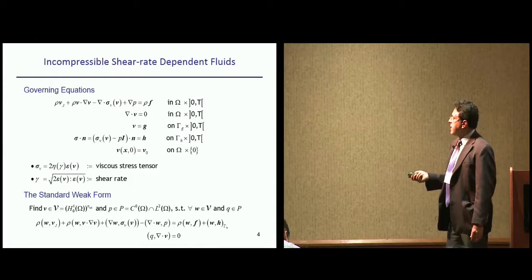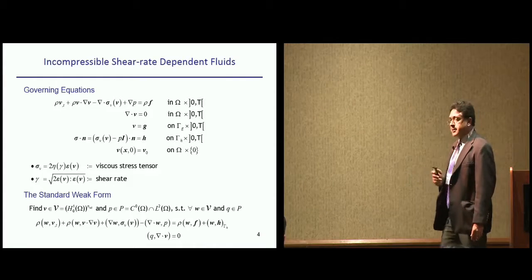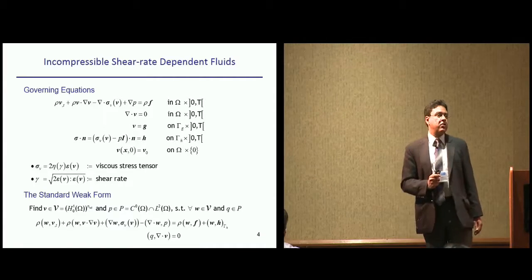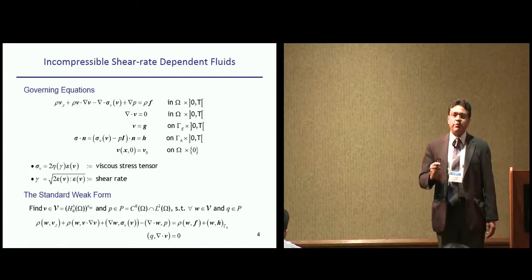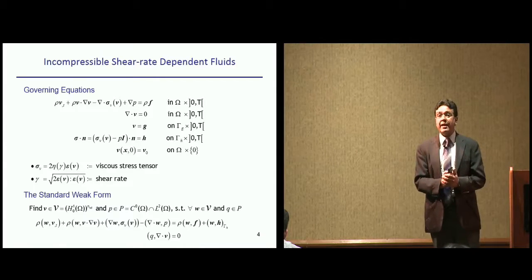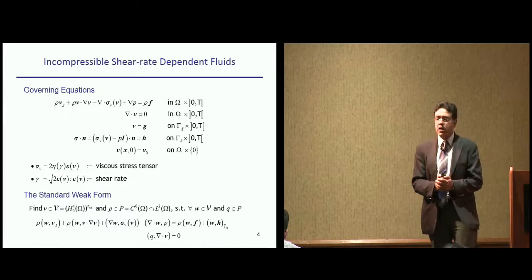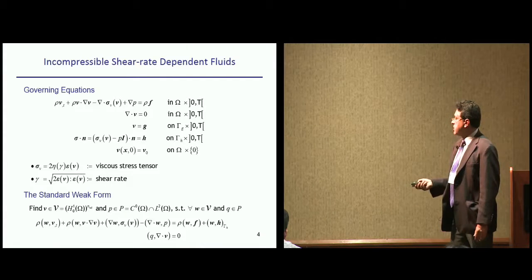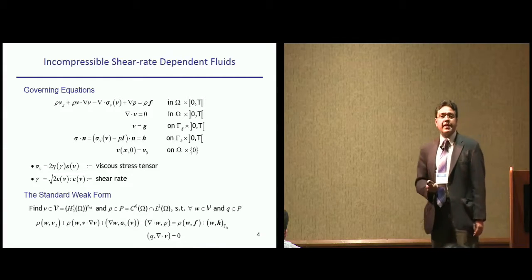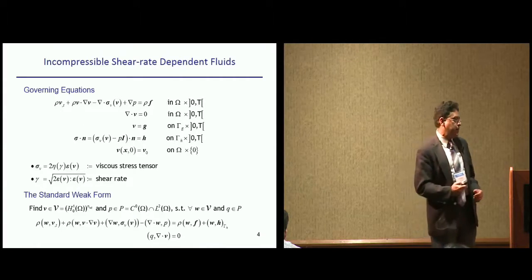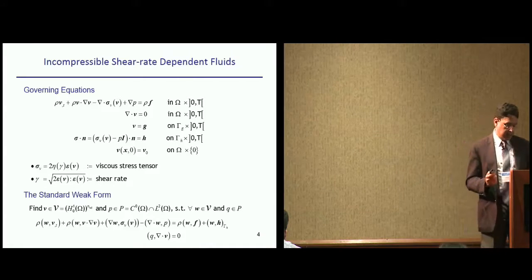If we develop the standard weak form, standard Galerkin form, which is the basis of developing the numerical method and also the finite element method, it looks something like this. In order to be able to develop techniques that will give us relevant physics without having instability issues in our calculations, we need to pay special attention to this nonlinear term, and for this particular case, also to the stress tensor, which is highly nonlinear as well. So the degree of nonlinearity or complexity of this model is a lot more.